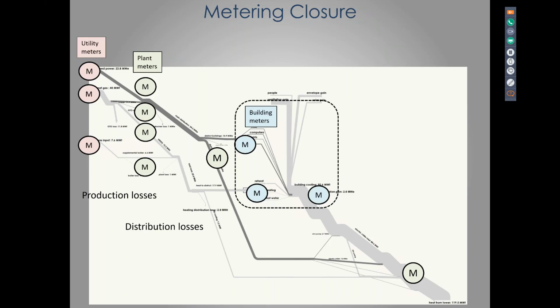And then what's critical too, and actually we partner with GLHN on this, on a monthly basis, because we also have auxiliaries. We're supplying chill water, we're supplying steam to a hospital. It used to be University of Arizona, it's spun off, but they still get utility systems through our distribution system and our production. Also our Residence Life, our Student Union, the auxiliaries. And so we do a meter verification every month. We look at every meter we have. If something is askew and not within the variance that's been established, we then can drill down further and find out what's going on. It just helps the technicians greatly with the electronic notifications they get, and also the verification in terms of financial, that what we're charging our customers is accurate.